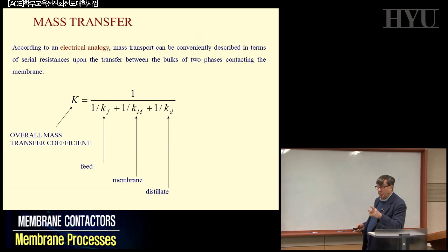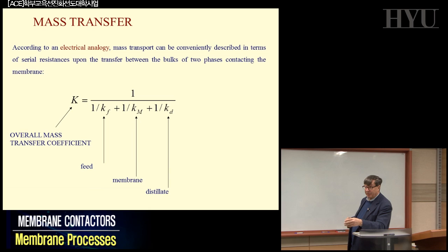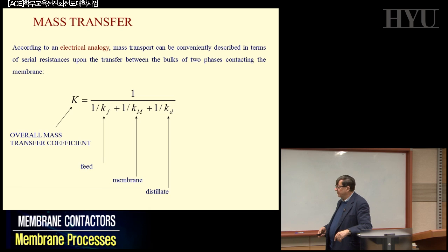Also in this case, we have to understand mass transfer and heat transfer, because in this case we are warming up one side of our membrane, which we were not doing in all the systems before: reverse osmosis, nanofiltration, ultrafiltration. We never spoke about delta T. The temperature on the feed side and on the permeate side was always assumed to be constant. If it was not, it is normally not very important, and we would have to consider in that case what happens in terms of the different temperature. But we never discussed it because it's not normally the case. Here, we have to consider both cases.